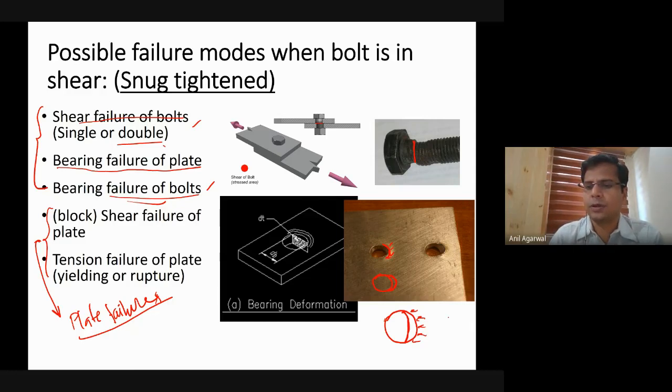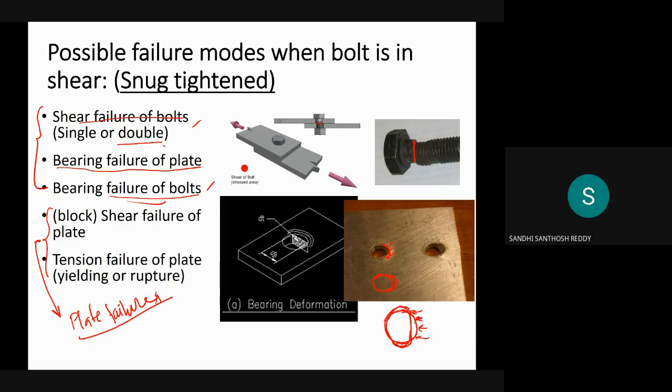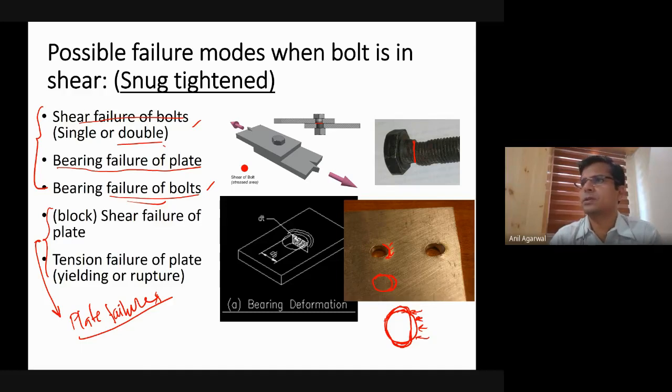So to start with, a bolt will have a circular cross section, but if you are applying stresses on this surface, there may be a case that the bolt will become flatter like this. Basically this material on the surface may yield and it will get deposited on the sidewards. It will flow to the side, just like this one. Okay, sir. So it will change its shape.